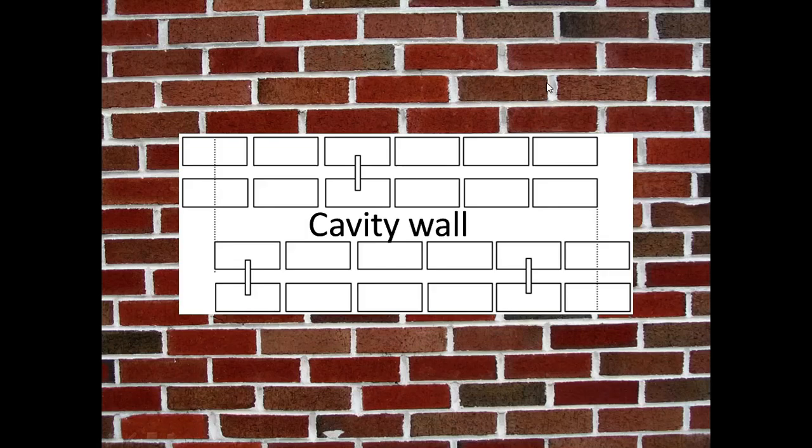It was discovered that the best insulator, of course, of all is air. So if you build two thin courses of brickwork and have an air gap in between them, you're building a cavity wall. Now structurally that wall works because every so often these two walls are tied together with little metal ties. You can't see them anymore. So when you look at a wall on the outside, if it's a fairly low building, say 3 or 4 floors high, and this will be true throughout the world, and you just see that, you can be fairly sure that actually it is a load-bearing wall.